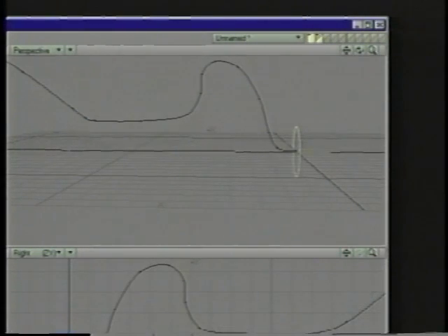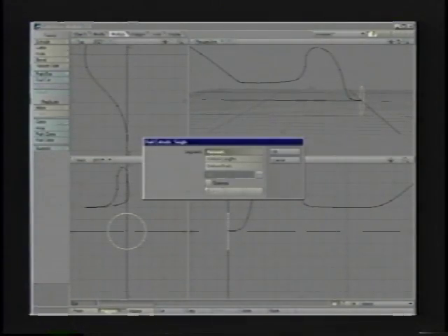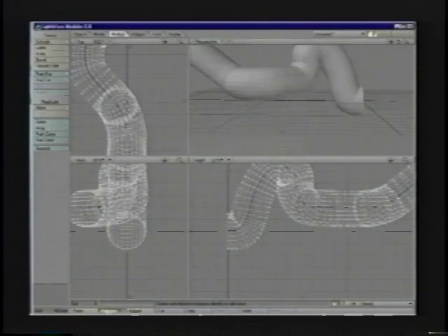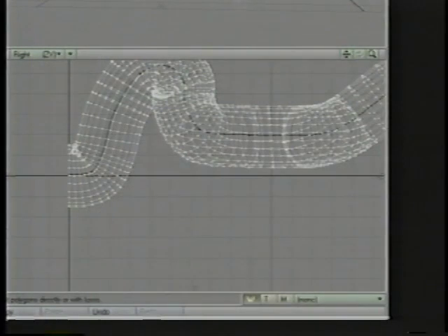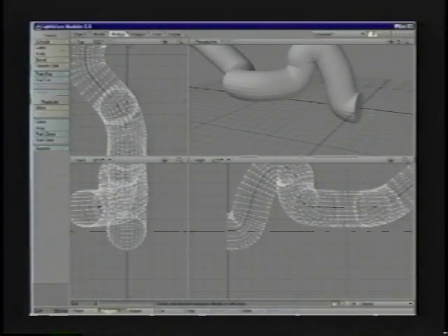If we undo that, now if I go back in and select oriented and say OK, you'll see that, again, it angles the disk around the curve, following the contour of the curve here. Sometimes you want that, and sometimes you want the other effect, but it all depends on the project you're working on. Okay, let's take a look at a couple of other tools.